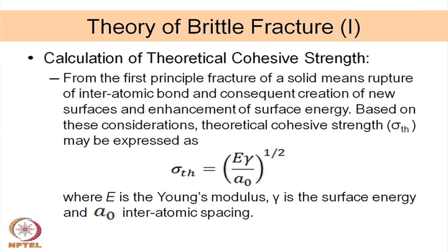Now, let us try to understand or calculate, from brittle solids or brittle fracture, how much is the theoretical stress required to initiate or to fracture a material. Calculation of theoretical cohesive strength: it is basically separating two atoms or two layers of atoms, and the bond energy comes into the picture.